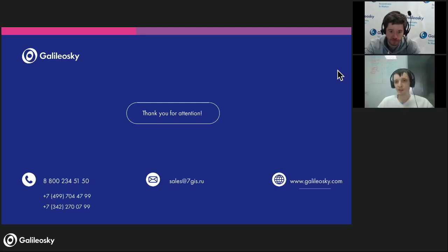Andrew, probably let me also add a little bit to Lauren's question. I wanted to clarify who this question was addressed to, the Galileosky or the Gutam team, because I think it was addressed to Gutam. This question is about notifications on fuel fillings and thefts. If we want to control a moving vehicle and we don't need to receive fuel thefts and fillings during movement, then just disable the time-based algorithm that I already covered, and instead use the mileage-based algorithm, when we compare the difference between the fuel levels within the parkings.